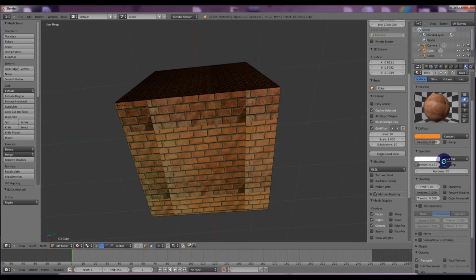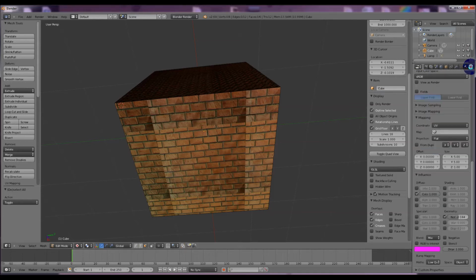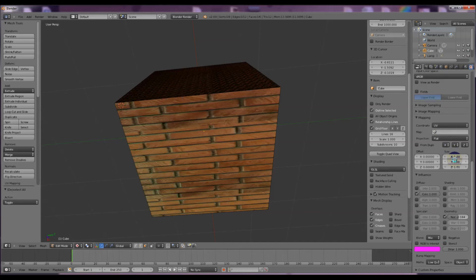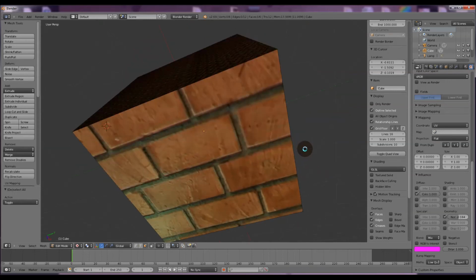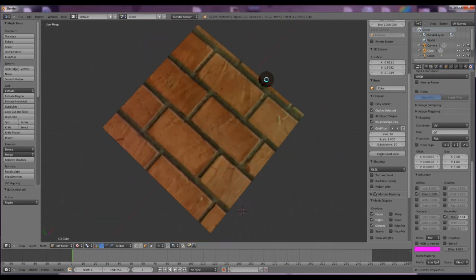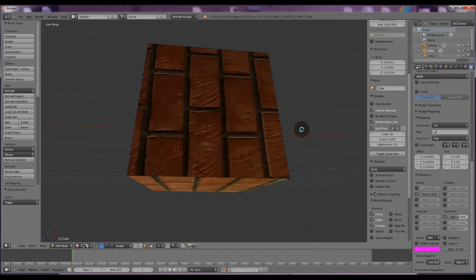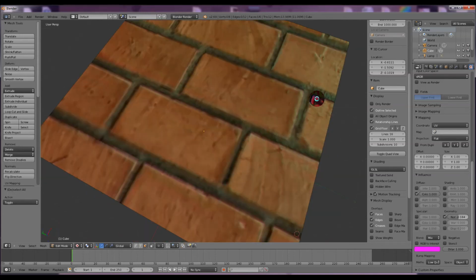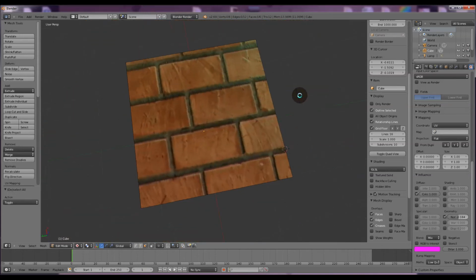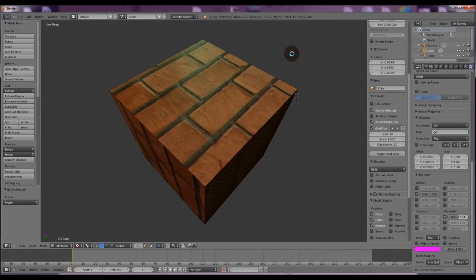Let's go back to the brick material, and then the texture. Let's just change that back to 1 because it fits on there better. Right. So we've got a UV and we've applied some materials to the surface. What we're able to do now is bake these materials into a single texture. Now this is useful because it gives you a complete texture that you're able to load on as a single material in the Blender rendering engine or in Cycles, which again we're going to cover later.